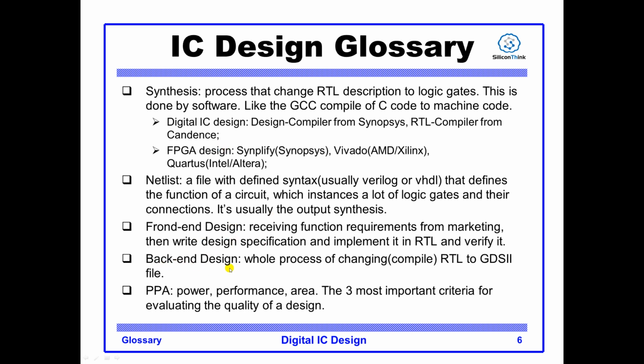Back-end design is also called physical design. This process is to change the compiled RTL, the netlist, to a GDSII file. Maybe from synthesis to the final GDSII files.